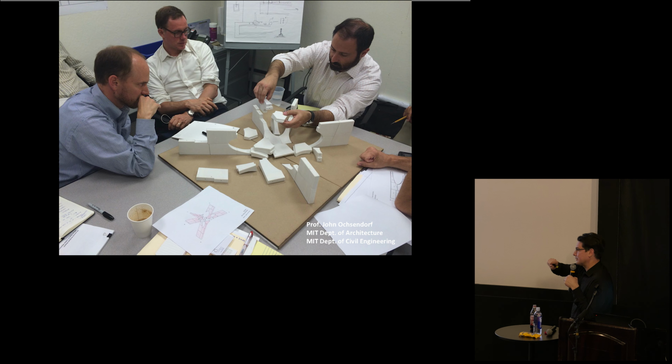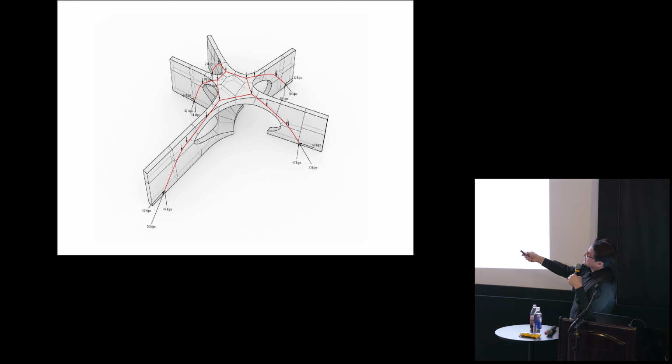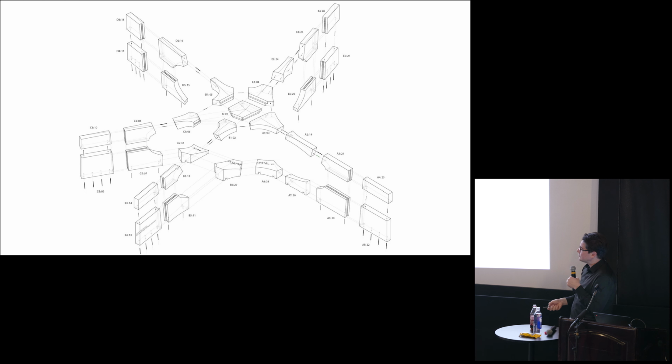It's a very low thrust. And so these calculations show the force vectors staying within the shape, within the form, but grounding all this force in the buttress walls. The length of the wall is a function of its resistance to the thrust line. And it's an irregular shape, this sort of five-sided figure, but the thrust lines are always perpendicular to that last joint. And so we figured out how to do an arch today.